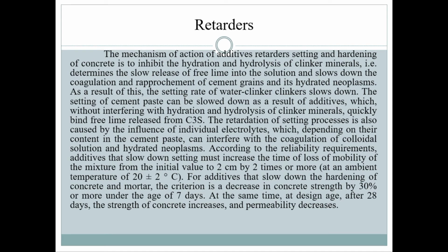The retardation of setting processes is also caused by the influence of individual electrolytes which, depending on their content in the cement paste, can interfere with the coagulation of colloidal solution and hydrate neoplasm.